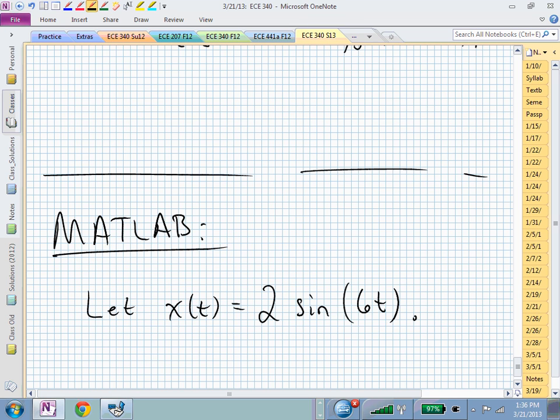And we're injecting a sine wave. So we're shaking it, aren't we? No, what is its frequency? 6 radians per second, right? So what is that frequency? 1 hertz. So maybe I was a little fast with my shaking.